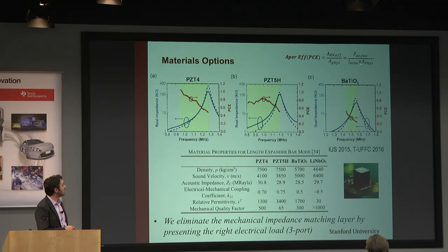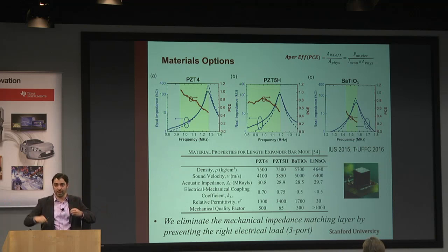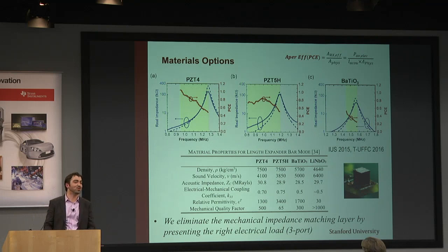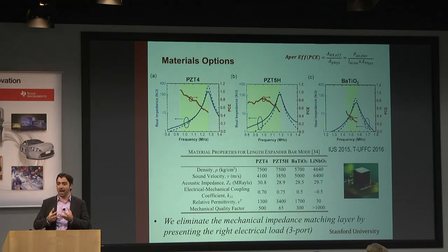If I get 100%, that means that all of the energy that came in that acoustic intensity, I can recover, right? So what you'll notice, which is interesting, is at some point your efficiency can actually go above 100%. And this could be exciting because why does efficiency go above 100%? Now, if you design antennas again, this is familiar because antennas that are small have an aperture that's larger than their physical area. If you think about a dipole, it doesn't have any area, but it still picks up energy, right? So in small antenna, quote-unquote, systems, you can get more than 100%, just meaning that your physical aperture is smaller than your actual aperture that's picking up energy. Sub-wavelength resonance happens in antennas all the time. So don't get surprised that our efficiency is going above 100%.